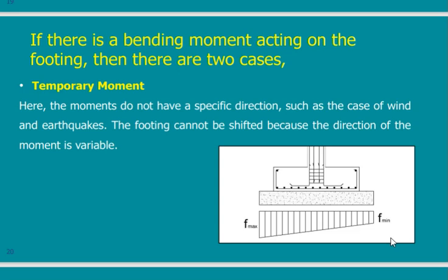Imagine that this is a footing, and I have a normal force in the middle of this footing. So the whole footing is inducing compression on the soil. If I start acting with a moment like this, and this moment is trying to overturn this footing, the moment, with the effect of the normal force, is just reducing the amount of the normal force in one direction.